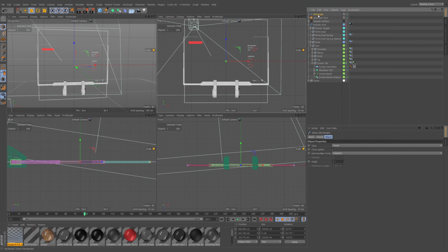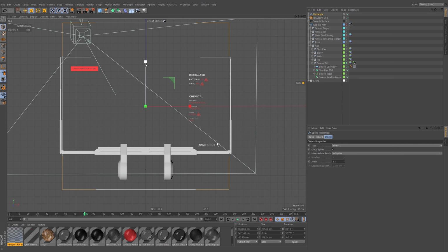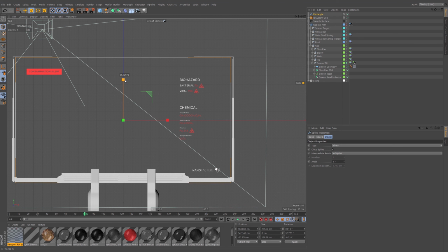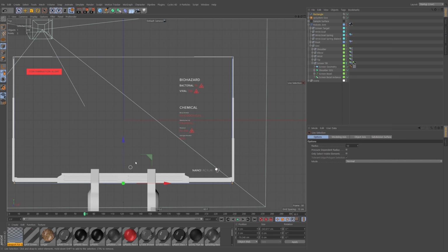Let's actually make it editable. Let's go to the full view. I can just use the modeling tool, scaling and stuff now, so it doesn't have to be completely perfect. It just wants to be pretty much aligned up with our outer edges here, just slightly indented. It doesn't matter if there's a bit of overlap. Then I'm going to go to points mode, select these 2 points on the bottom here and just bring them up slightly. There we go. We can adjust these later if it's not looking right.